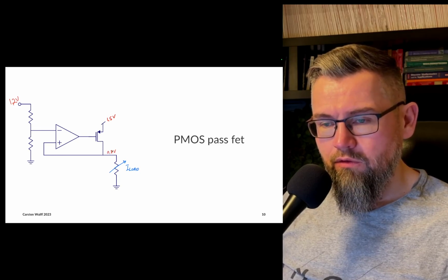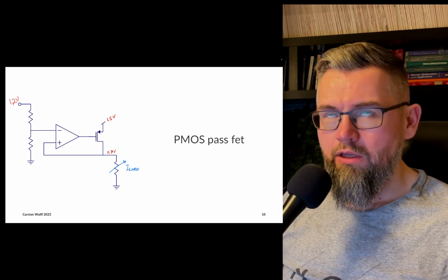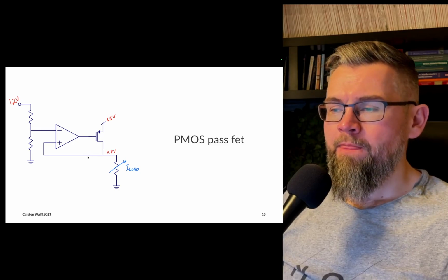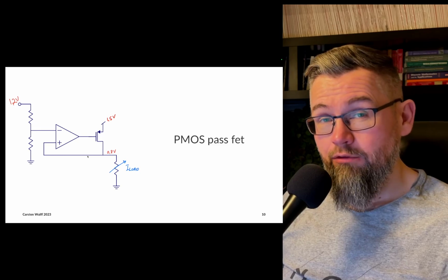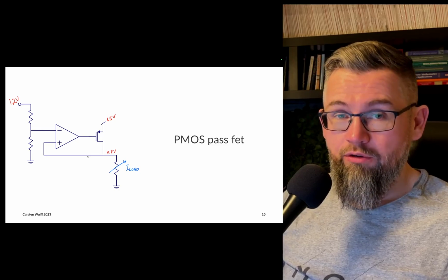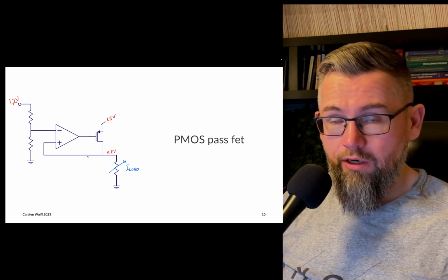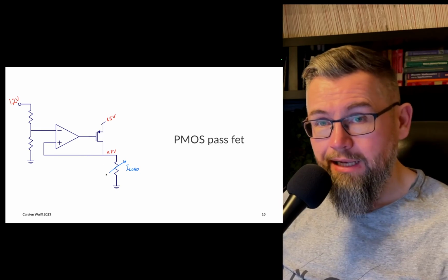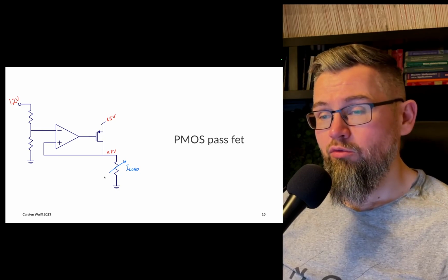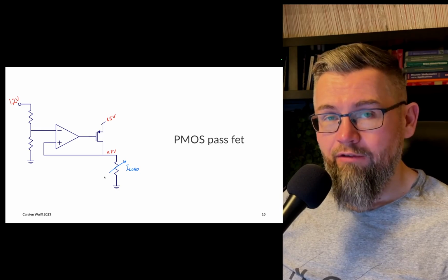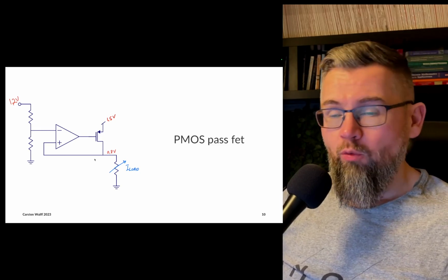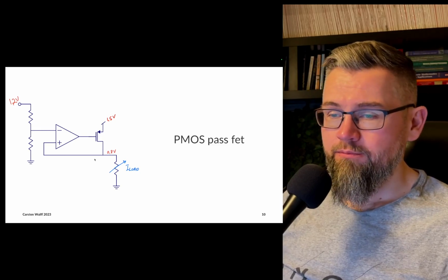voltage controlled current source. So at all times, it tries to adjust the current through the PMOS such that you will get 0.8 volts. Now, of course, in a system like this, you will have a certain bandwidth of the op-amp, which means it can't be infinitely fast. And maybe you have to deliver really fast load transient currents, like to a CPU, which clocks where most of the current is when the clock strikes. But maybe then you add a capacitor to ground and you use that capacitor as a charge storage device to provide the electrons when you have very fast transients. And then you use the feedback loop to provide sort of a slower control of the output voltage.